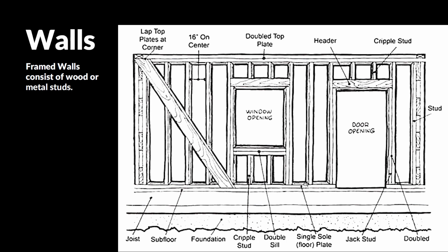On top of that, we can put our vertical studs that are spaced 16 inches on center in standard new construction. Older buildings, when you get into renovating older structures, you will find there are a lot of inconsistencies, but newer buildings should be 16 inches on center from stud to stud.